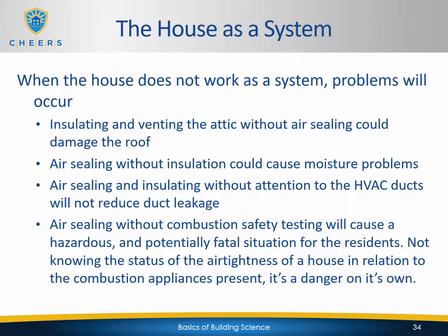And then air sealing without combustion safety testing will cause a hazardous and potentially fatal situation for the residents. Not knowing the status of the air tightness of the house in relation to the combustion appliances present is a danger on its own. It's not necessarily that it's going to happen, but the reality is that it might happen. And not knowing whether it does or not is dangerous on its own. Anytime you air seal, you absolutely should test the house to make sure that the combustion appliances are working properly with the new air sealing.